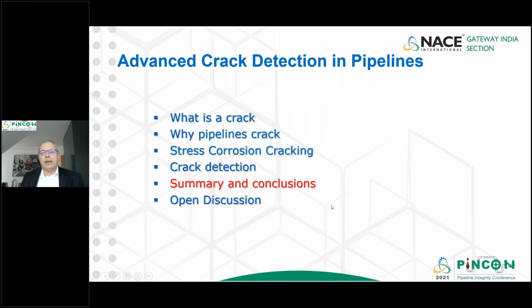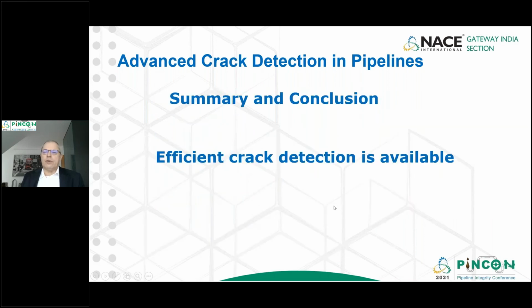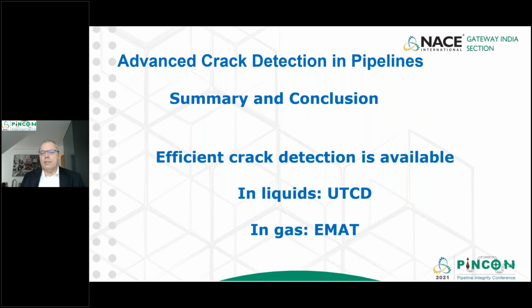To come to the end, efficient crack detection is available for liquid lines and for gas lines. In liquids, it is the ultrasonic crack detection tool. In gas, it is the EMAT tool. Both methods have a high accuracy in detecting and sizing cracks and also crack-like features.